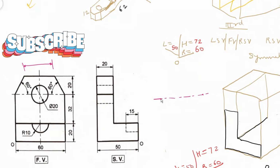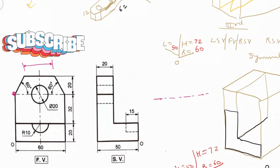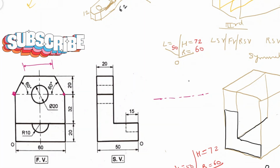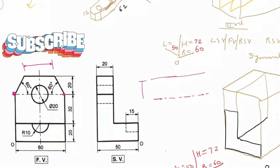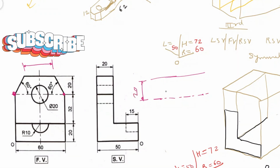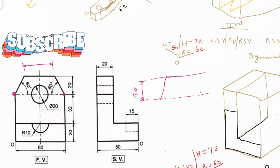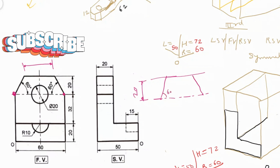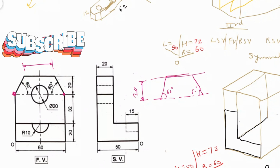Now this point is which point? This point is this point. See in the isometric, in the object, this is the point, and this is another point. Now from here, what I have to do? I have to draw a vertical line of 20 mm. So I have drawn a vertical line of 20 mm. So this is the distance of 20. You have to actually draw this in the examination also. And then from here, you will draw a line at 60 degree, and from this point also you will draw a line at 60 degree. And now we got this point.